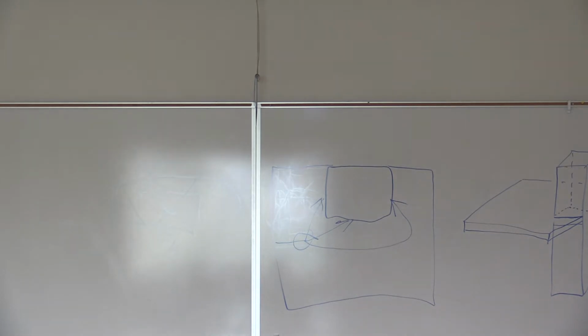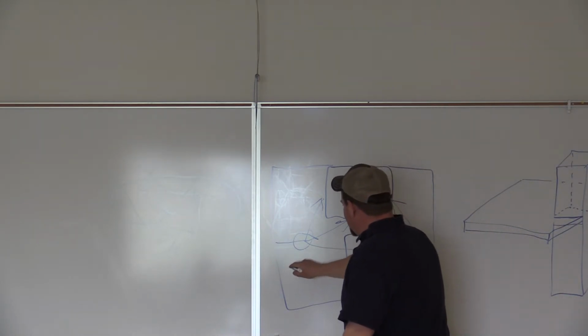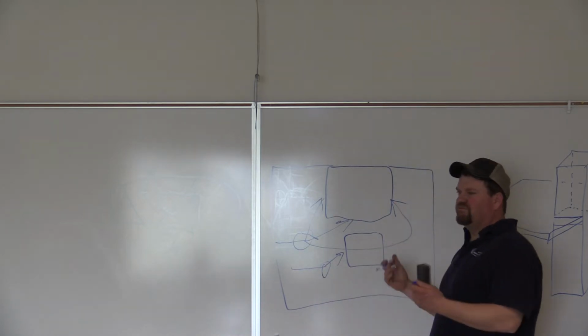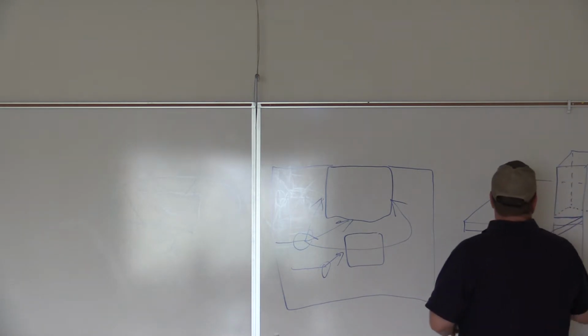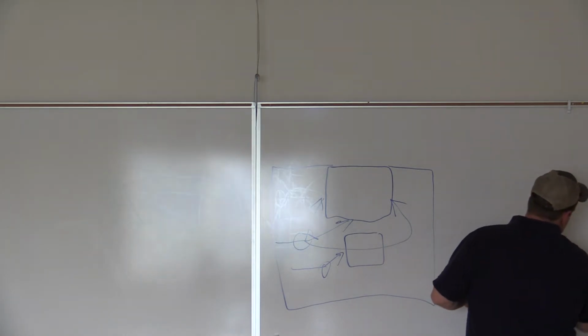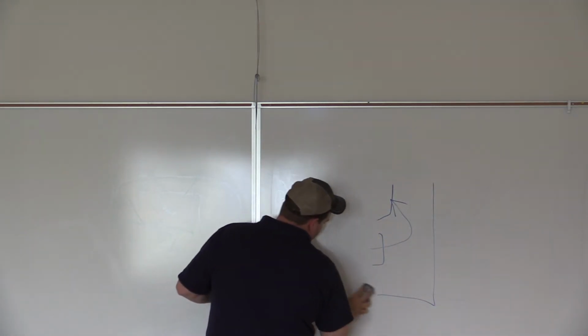So other than that, if it were in the center of this piece, right in through here, then it would be really simple. Just tell you weld all the way around, you weld all 4 sides all the way around. Okay? That's typically when you're going to see multiple arrows. Okay?